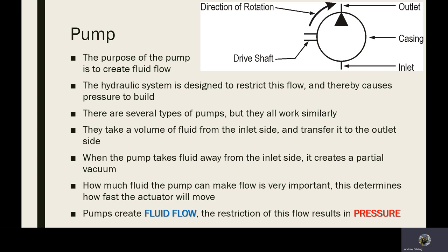There is a fluid intake from the inlet side. Generally, if it's a gear pump, it would go around both sides and then it would spin it out the top. If it was a volute pump, it's using centrifugal force, it sucks it into the middle and it slings it out to the outside, where it's then directed through the volute and out into the rest of the system.